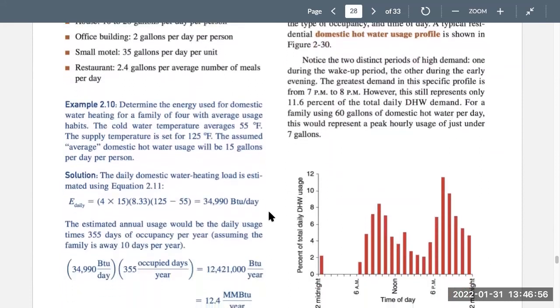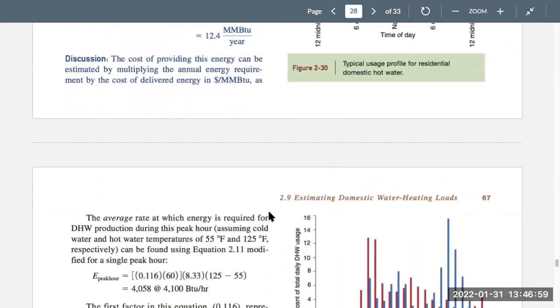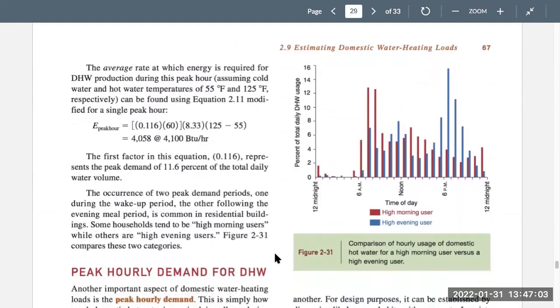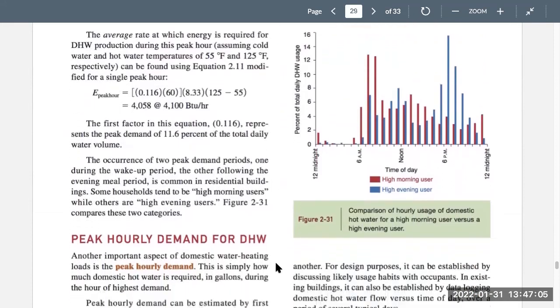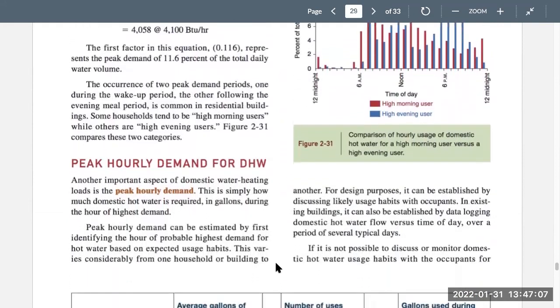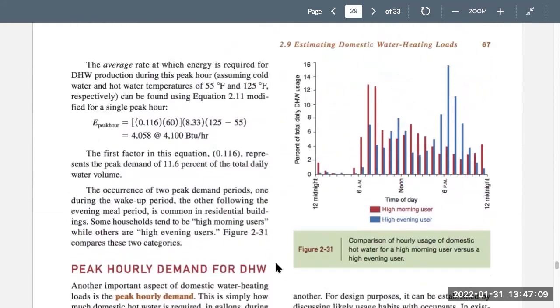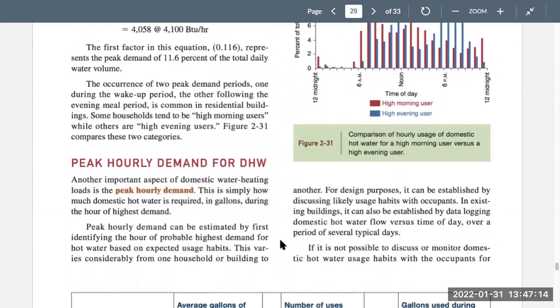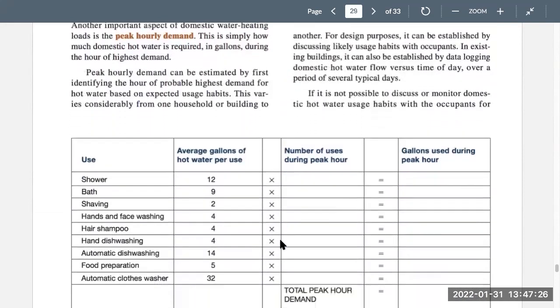It's going to be based off of occupancies, how often you use your water, how many people are in it. And it gets really complicated just trying to guess how to do all that when we can put a kilowatt meter on their hot water heater and leave it on there for 2 weeks and have a really much better idea of how much power their hot water heater is using, instead of going about it this method.